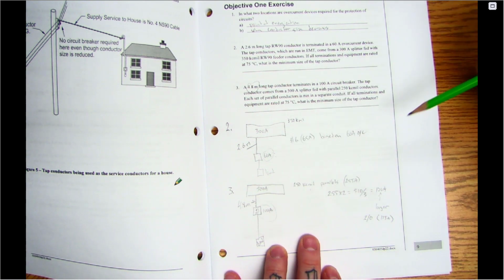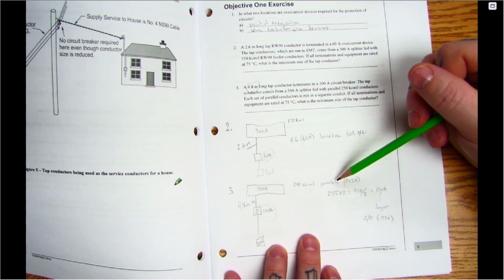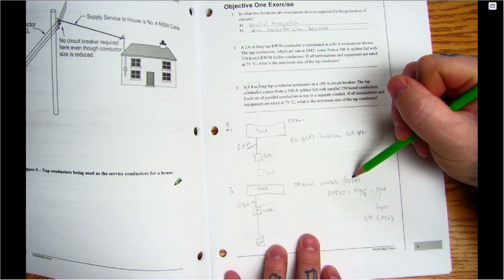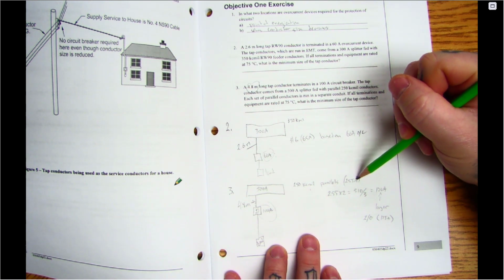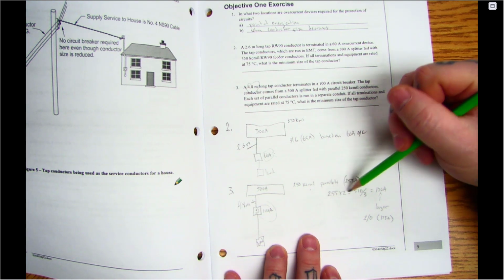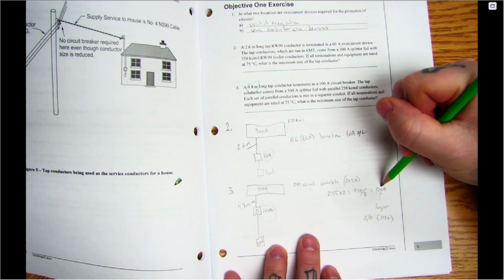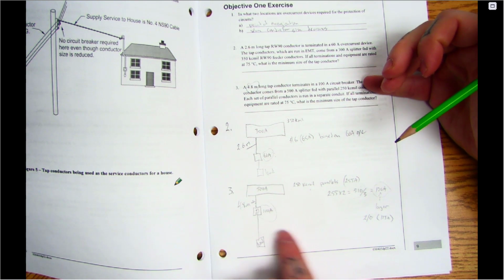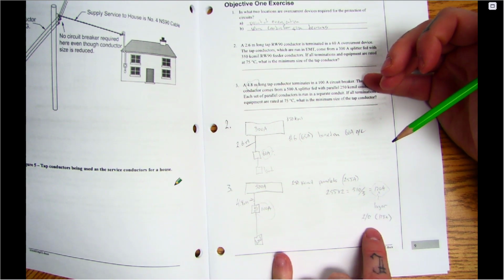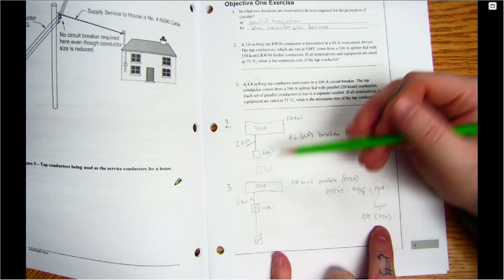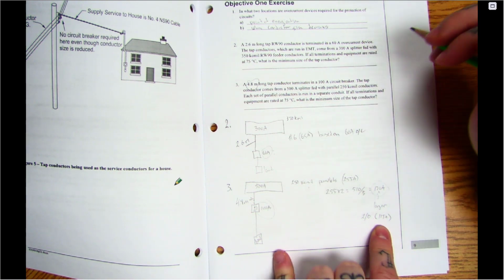So we're looking at the 100 amp, and then we compare that to 1/3 of the conductor ampacity. In this case, it's the 250s. They're good for 255 amps, but they're parallel runs. So I take that 255, times it by 2, and I get 510 amps. Then I divide that ampacity by 3, and I get 170 amps. That's the other number I'm comparing. So I'm comparing between the 100 and the 170. The 170 is larger, so I go to Table 2 at 75 degrees, and I'm going to have to use 2 aught there because it's rated for 175. Still large, but definitely not as large as running parallel 250s.